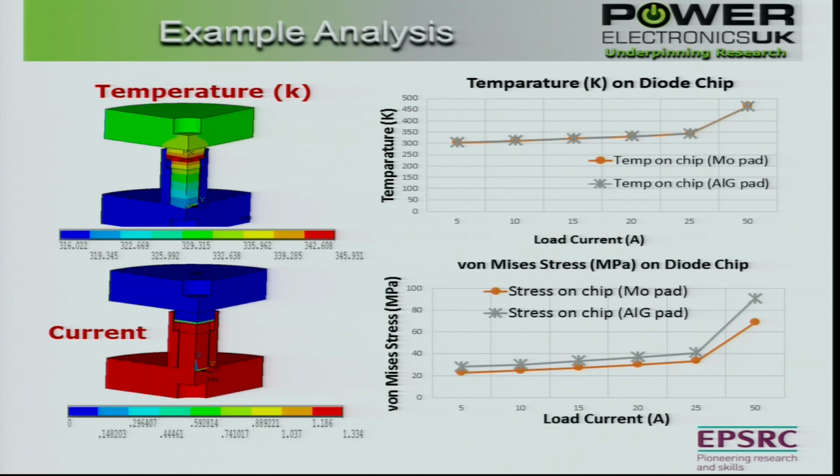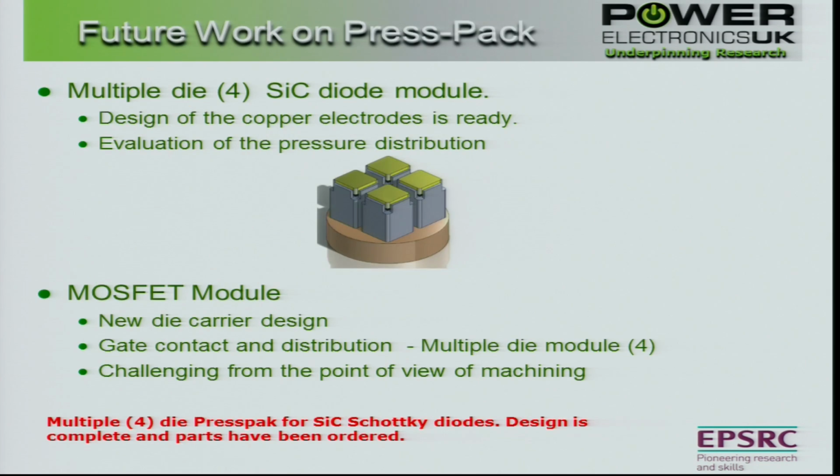So it looks here, for instance, that the lower stress comes with the aluminium graphite, and therefore that may be a better solution, but it's not necessarily absolutely the case. I guess we need to look at other factors here, but a first cut of this says that the aluminium graphite maybe is the better solution for the contact material.